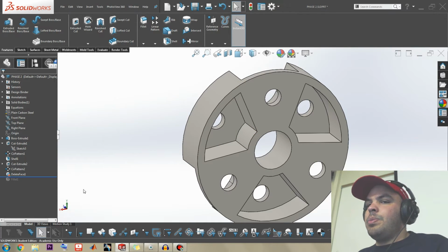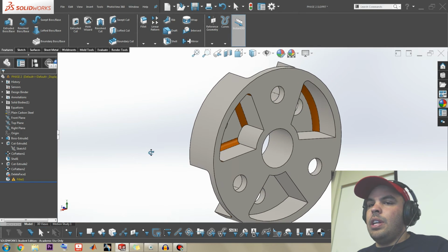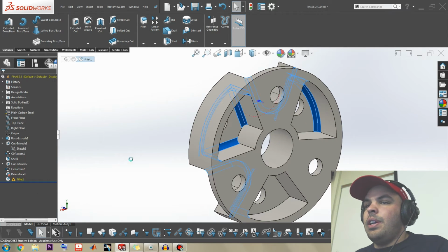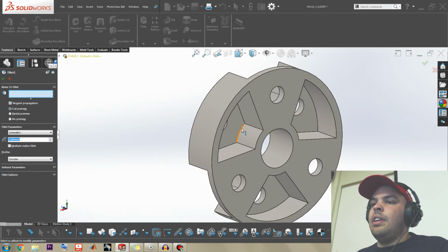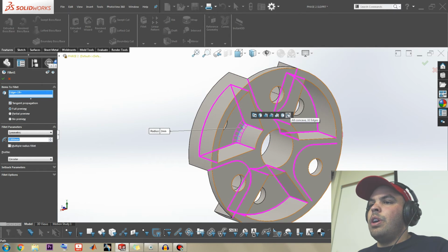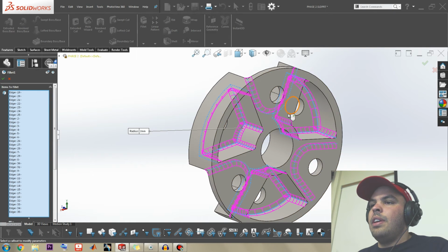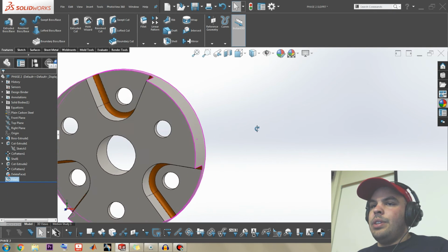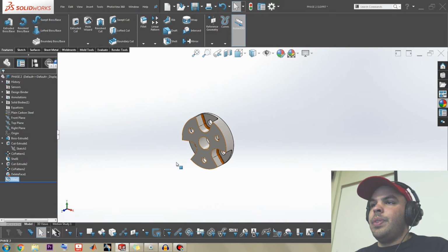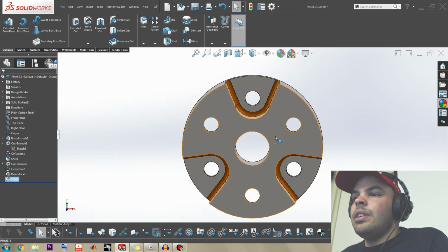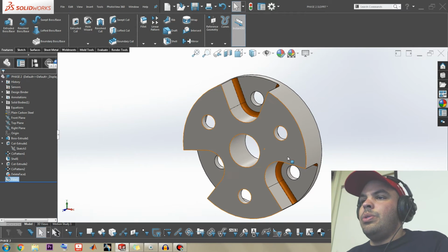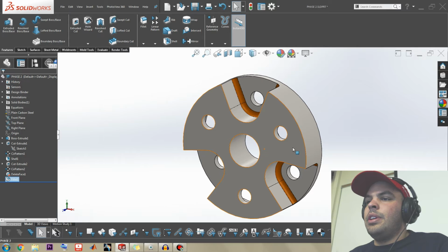So now at this point, we have to repair our fillet. We unsuppress, and we can see that it's unhappy with us. That's fine. And very smart thing, he just clears selection, and the same pattern goes for all of this. It's all the concave edges, and just like that, he fixes the fillet. And that's the end of phase 2, actually. So now we go on to the simulation part.